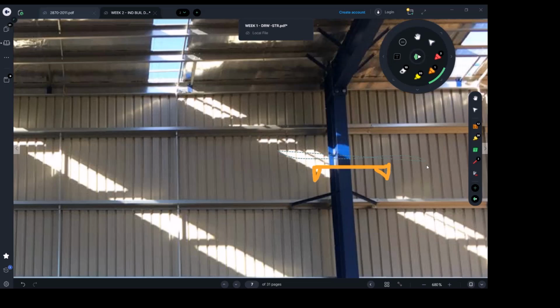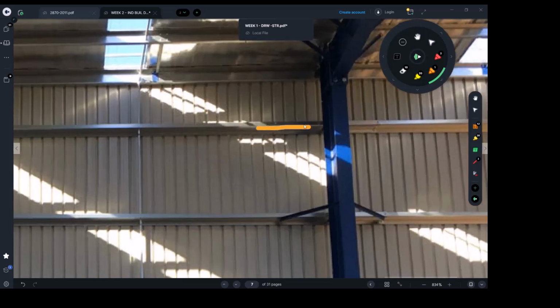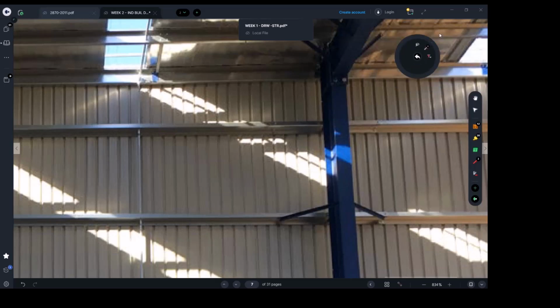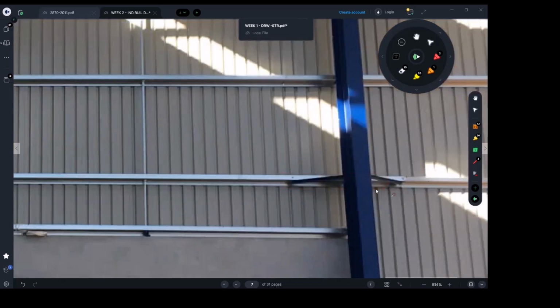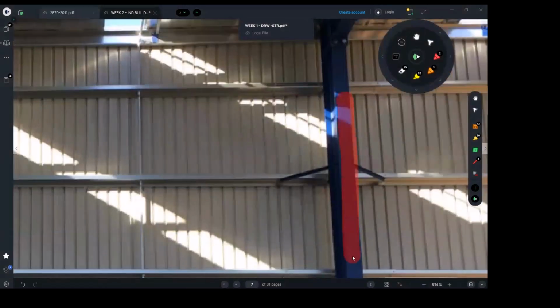So what I'm trying to point out here is, when engineers, and same as when the construction engineers build this, they need to understand that those girts are not just connected to vertically carry themselves. No, the girts are actually helping the column, because the girts are going to tie it. Now, the back flange is actually restrained over these distances, which is say about a meter. Okay. However, the front flanges here are braced by the fly bracing, these guys.